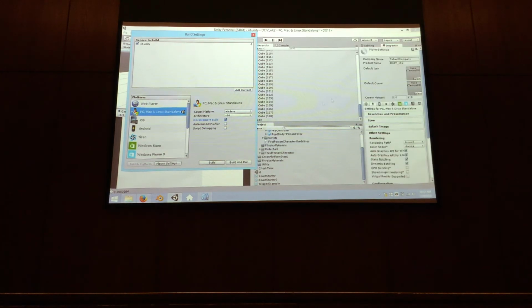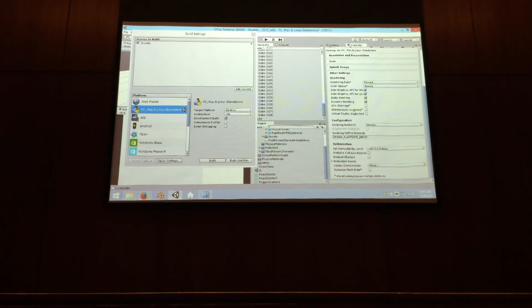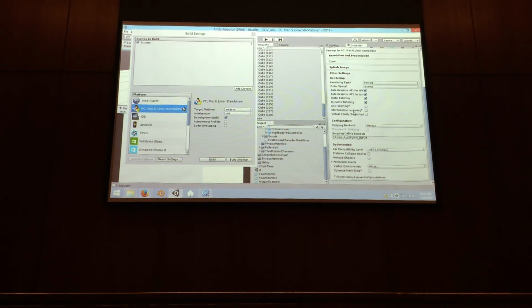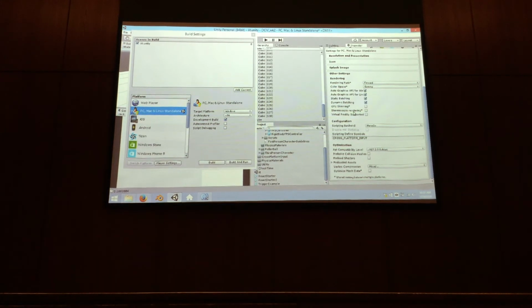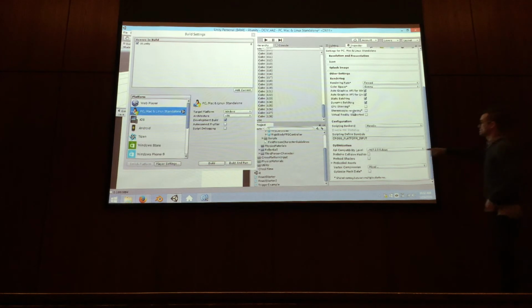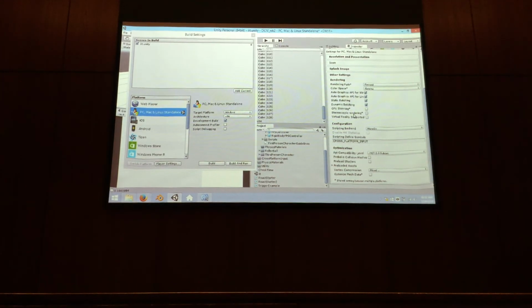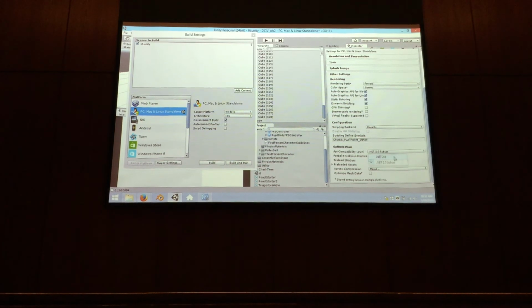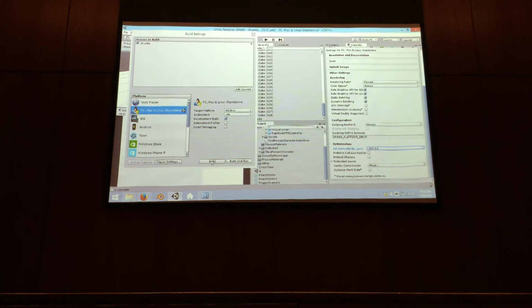And then the other thing you can look at here is the player settings. This won't be such an issue now. All the defaults will be fine. But when we move into the final phase, when we start to connect the Arduinos to Unity, we're going to have to make sure that we're not using the .NET 2.0 subset, but that we're using the full .NET 2.0 library. Okay. Now I say build,